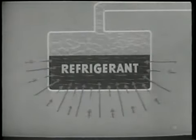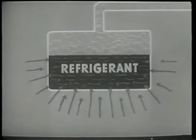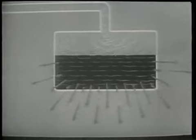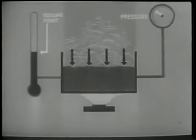The principles of refrigeration are physical principles applied as follows for the purpose of removing heat and reducing temperature. First, mechanical refrigeration rests on the ability of a refrigerant to absorb heat while changing from a liquid to a gas and to release that heat while returning to the liquid state. Second, when the pressure on a liquid refrigerant is reduced, the liquid boils at a lower temperature. Third, the transfer of heat from food items or other warm surroundings to a liquid refrigerant involves three processes: